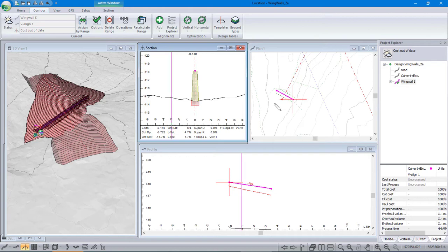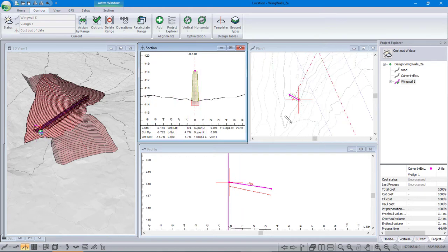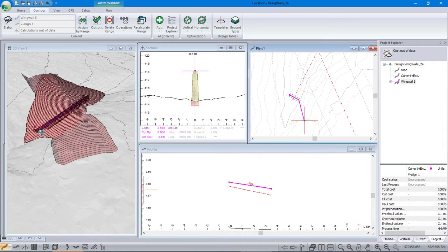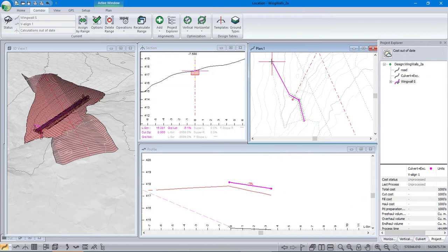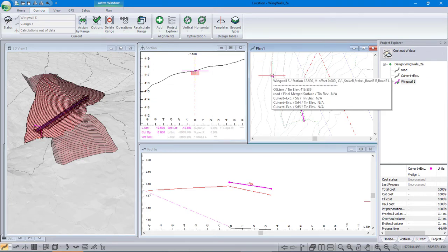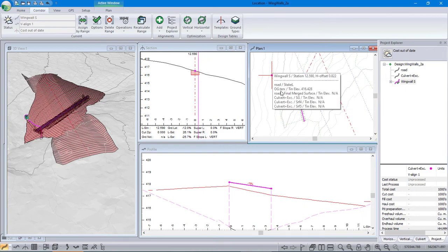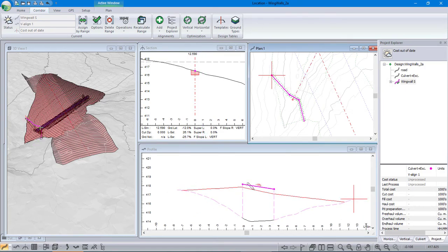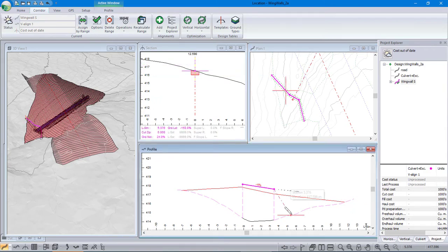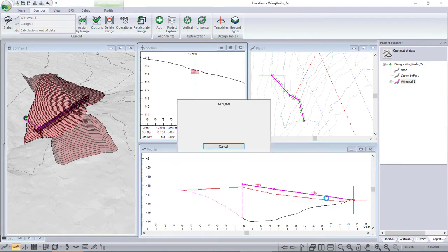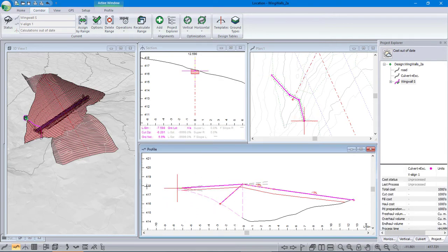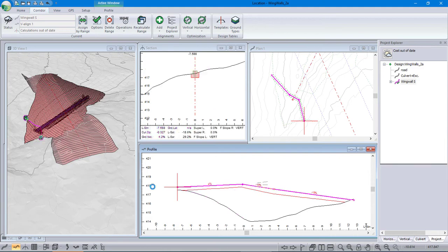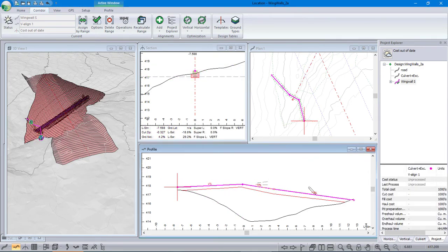Now we need to extend it right to the edge of the slope stake for the road, so we catch all the fill. So I'll extend it this way, roughly parallel to the road, and similar over here. I think I'll go to that point there. Again, I'm just outside the road slope stake, and you can see that now when I finish my vertical alignment like so, my wall, whoops, is above the road surface, the road fill surface all the way from one end to the other.